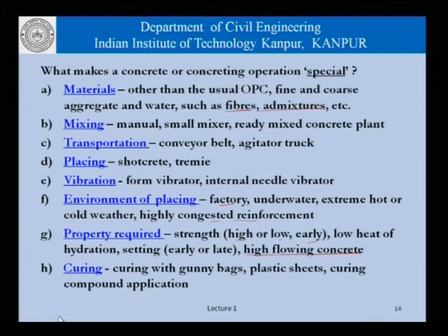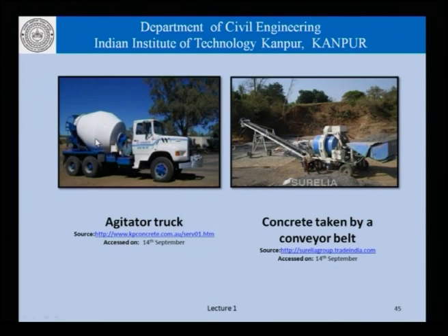So that's about mixing. Now let's look at transportation, how concrete is transported. This slide here shows transportation of concrete using a conveyor belt. This picture here on the left shows concrete being transported with an agitator truck. This drum here has to be kept rotating in order to ensure that the concrete does not set and stick to the sides of the drum.